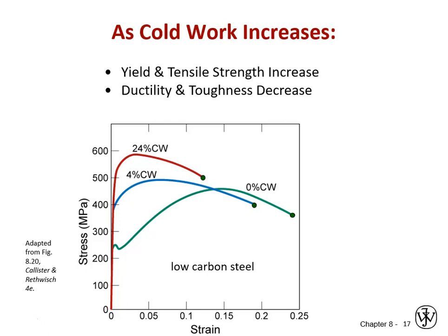So we're not looking at grain refinement here. So everything else being the same, we have one that's as cast, 0% cold work in the teal curve, one with 4% cold work, so we've increased the dislocation density and we've moved a few, piled them up at those grain boundaries, made them interact with a second phase, whatever.